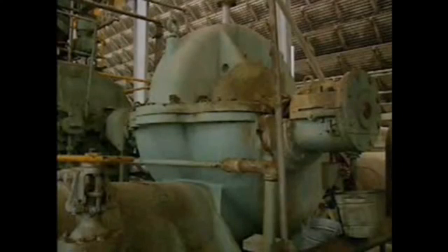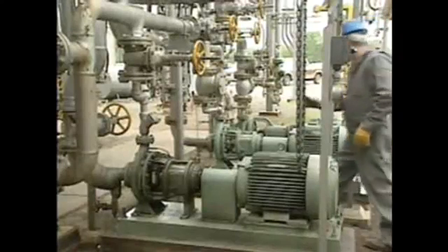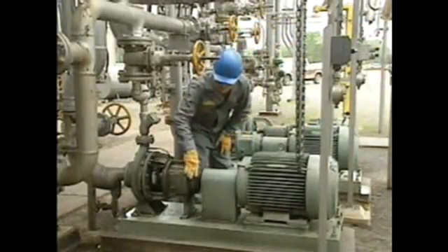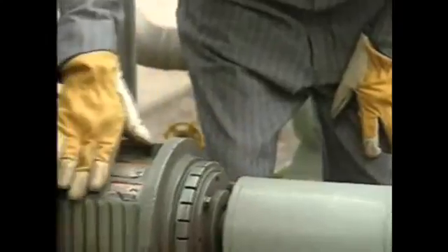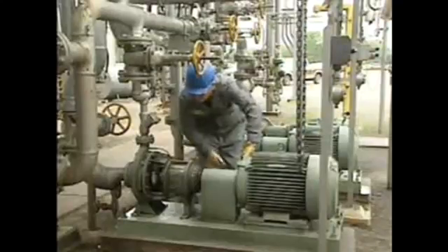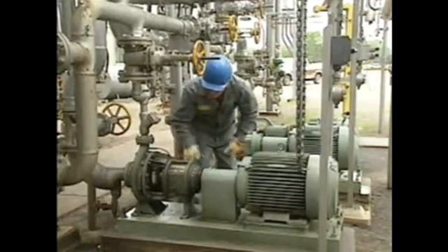Rolling contact bearings can last for years, but eventually all bearings fail. There are several factors that can cause bearings to fail and several specific types of bearing failures. Usually, it's possible to tell a bearing is failing before removing the bearing from the machine. Bearing failures are often accompanied by high levels of noise or vibration, high operating temperatures, and the smell of burnt oil.